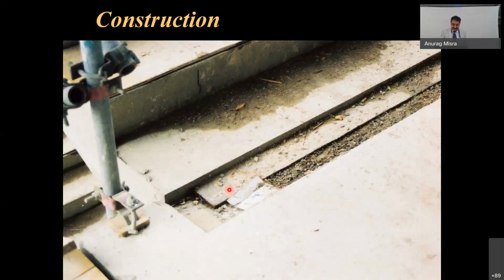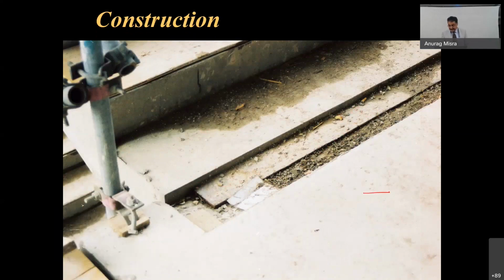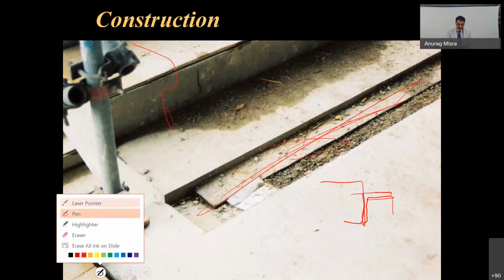This is the precast stair. You can see that this has been placed. There is a steel bracket attached. This bracket is actually like that, which is embedded into the concrete, and then it is placed here so that the stitch concrete or finished concrete could be placed here for making it a plain surface, and you would not know whether this stair, with these steps going up, is precast or cast in situ.